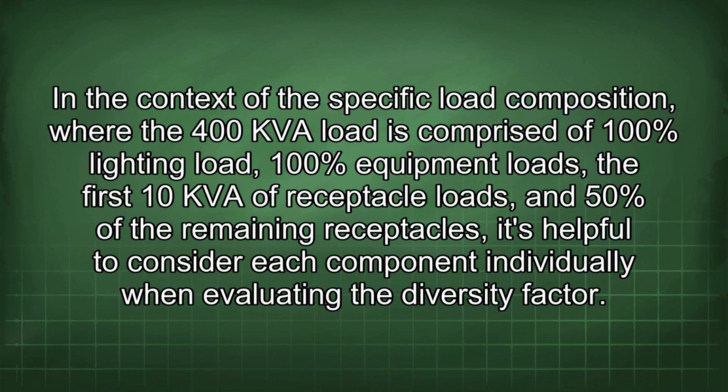In the context of the specific load composition, where the 400 kVA load is comprised of 100% lighting load, 100% equipment loads, the first 10 kVA of receptacle loads, and 50% of the remaining receptacles, it's helpful to consider each component individually when evaluating the diversity factor.